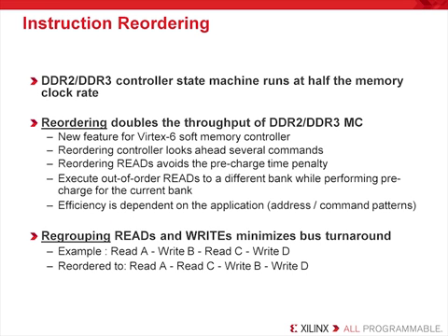We now want to take a couple of minutes and tell you about some of the new features of the Virtex 6 memory controllers that are made with the MIG. The performance of the Virtex 6 base controllers for the DDR3 and DDR2 is half the memory system frequency. This is possible because the memory specification does not require commands to be issued at full frequency for the DDR2 and DDR3 standards.